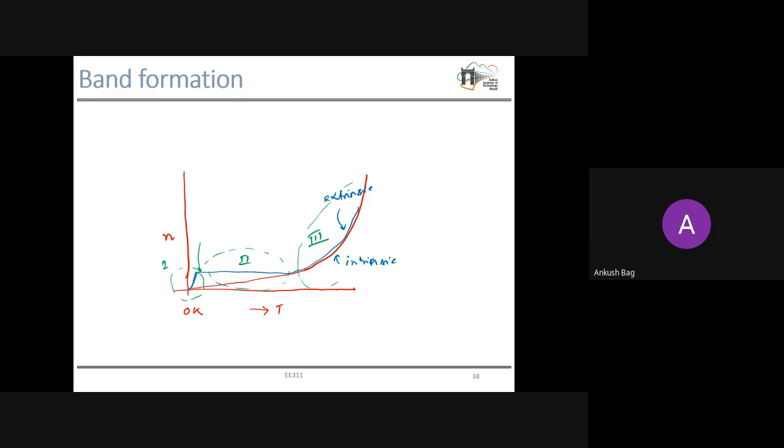From your understanding, I think you can guess that we are using our semiconductor in this particular domain, when our temperature range is within this second domain. Why? Because in this temperature range, the carrier concentration is constant. So here I have not mentioned other temperatures. Typically here, in case of silicon and arsenic, we have room temperature, that means 300 K.